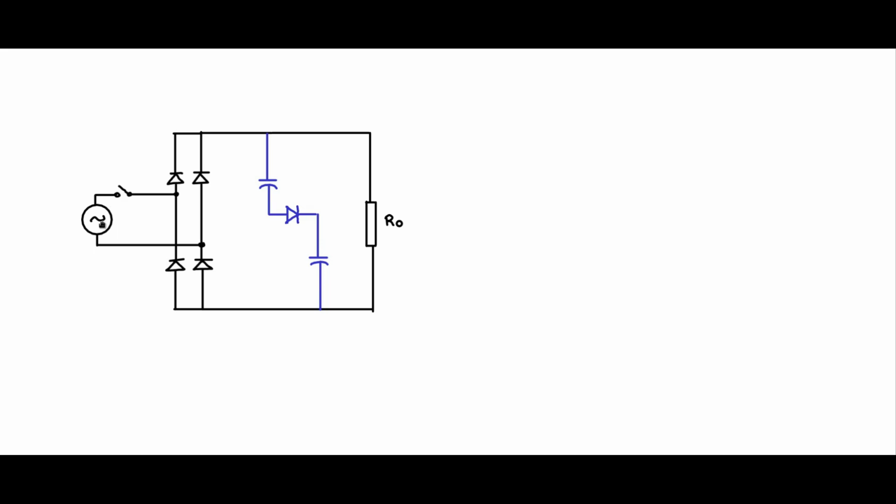So when the capacitors are getting charged, they will charge up in this fashion. However, there is no discharge path into the load because of the presence of this diode. There is a reason, we will see that. Charging is happening in this path. Half the charge will come into this capacitor, half the charge into this capacitor. So if you are having V0, each will take V0 by 2.